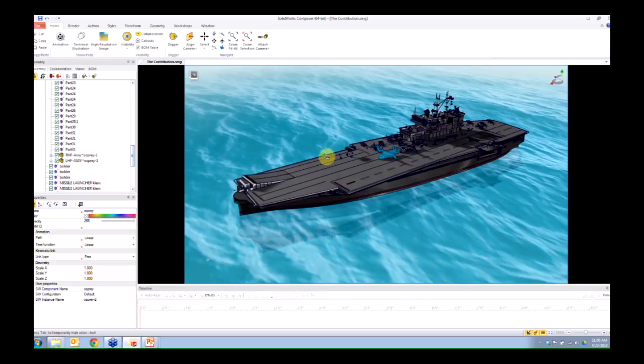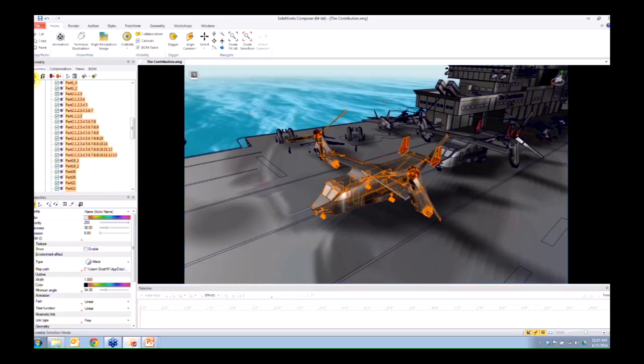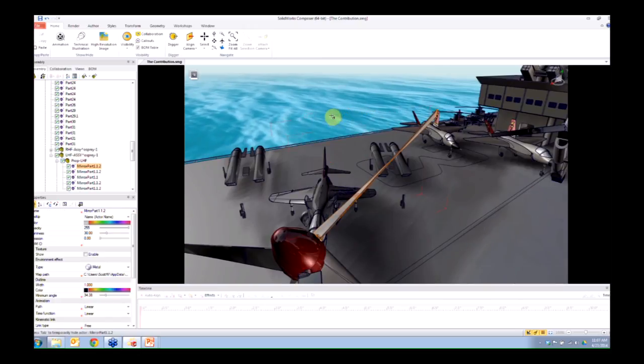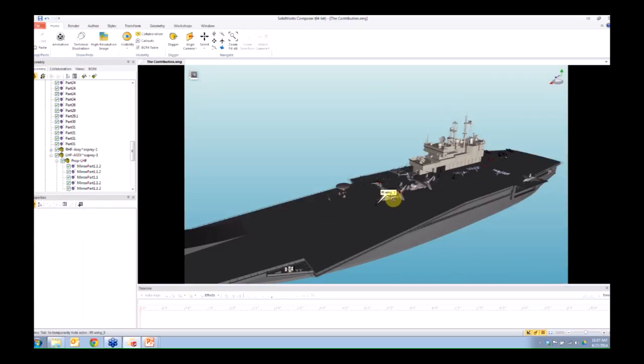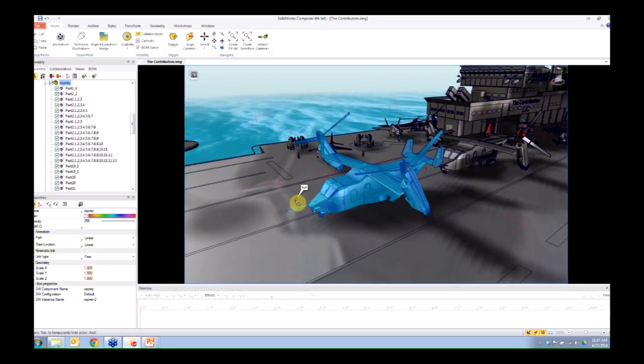So with that selected, let me go ahead and just double click that guy so we can zoom in here. Since I had the selection mode selected, with this assembly selected, I could zoom to fit just by double clicking it. If I did not have assembly mode selected, you'll see that it selects all the parts. And if I were to double click a part, it's going to zoom into that single component. With the sub-assembly selected, I can just double click it and I get the entire assembly, because it's zooming to fit the assembly and not the part.